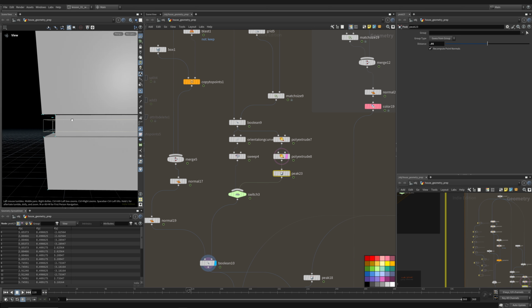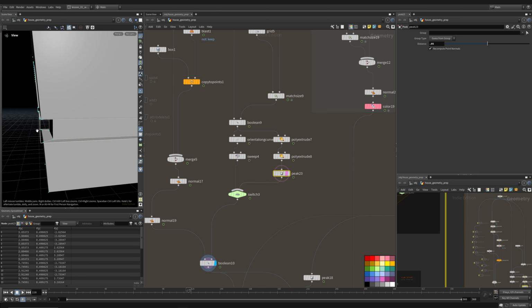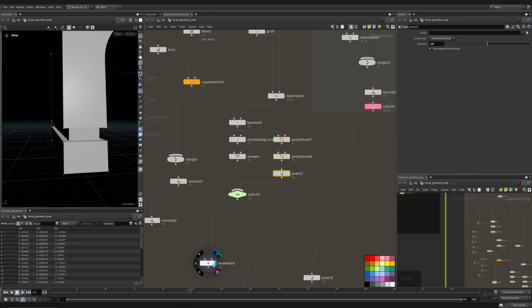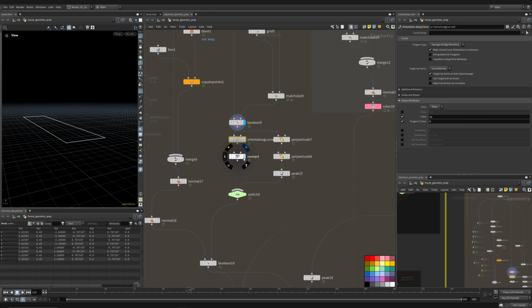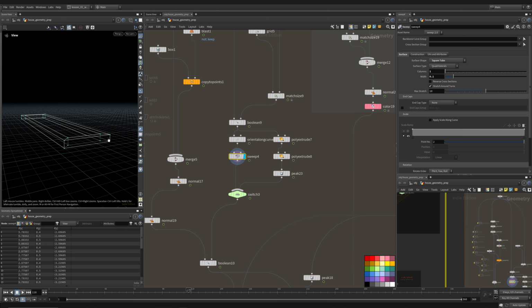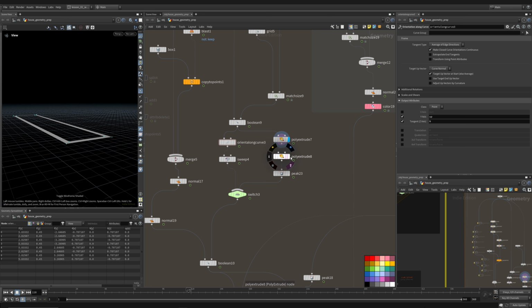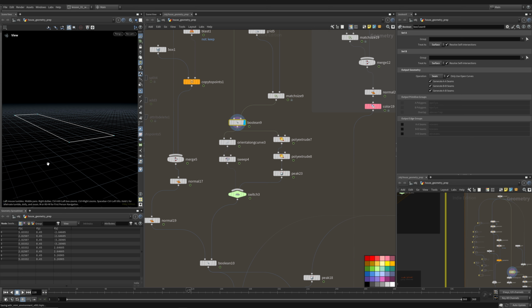And there we go. Now we Boolean it, and because this cutting area is farther than the inside of this object being cut, we'll have a clean cut there. So that's another way to do it. You can either sweep objects, sweep geometry around a curve, or you could actually use that curve to create the geometry itself. And there's really no correct way to do it.